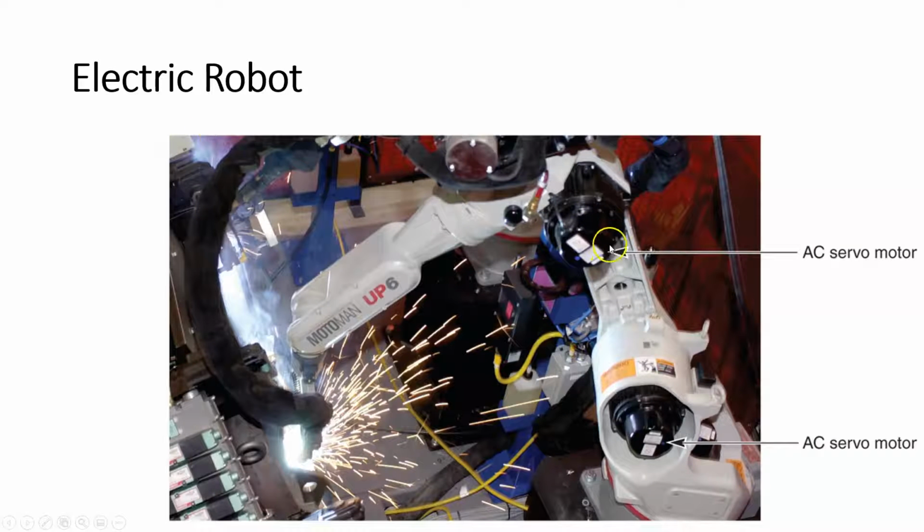With the electric robot, we always have to be cognizant of the electrical charge and whether sparks, not these sparks, this is a welding robot, but sparks from the motor are going to be safe. And so in a pneumatic robot, we have a safe operation with a clean robot, and that's kind of where pneumatic robots are going to fit in. But again, they typically are smaller robots.